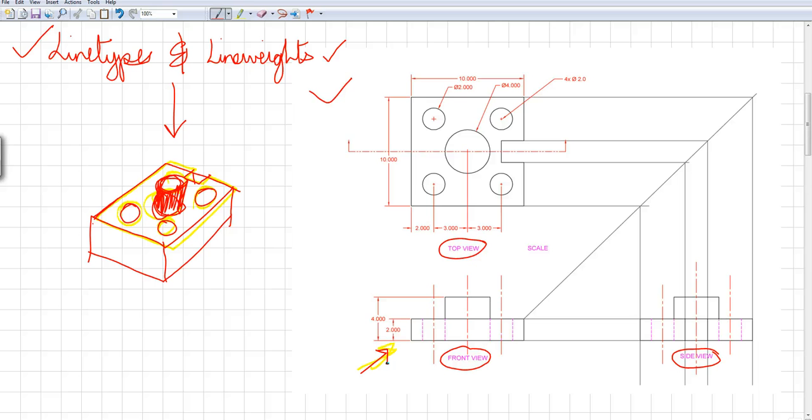So what do I see in the front view? So in the front view, I'm seeing this base, which is again this base, right? Front view, I'm looking that way. Then I see this cylinder, which is that cylinder, okay, the big one popping up. And then I even show some dash lines, 1 and 2, right there. And those dash lines are for these holes. But if I'm looking this way, I'm just seeing this surface.